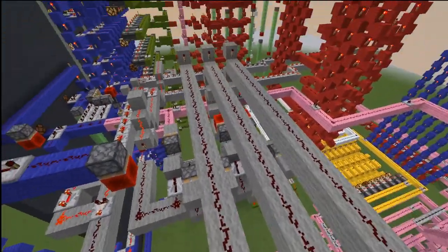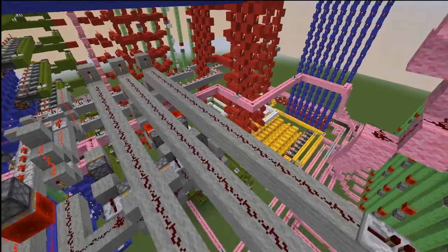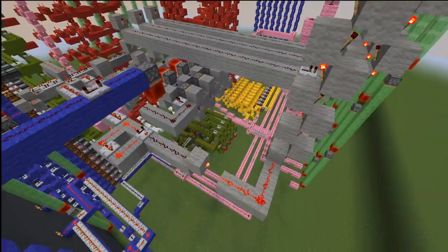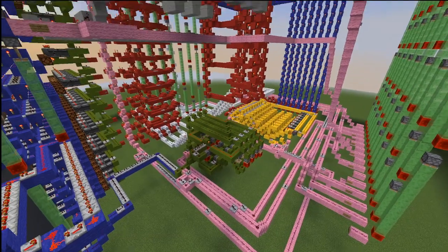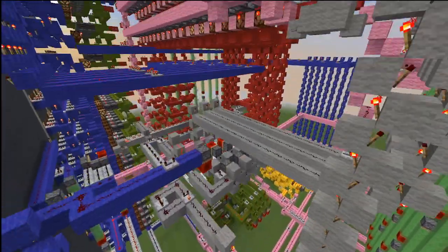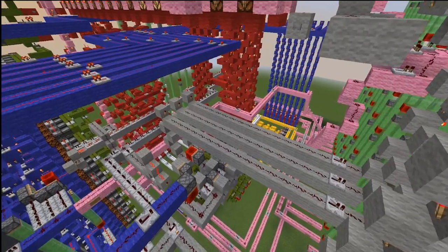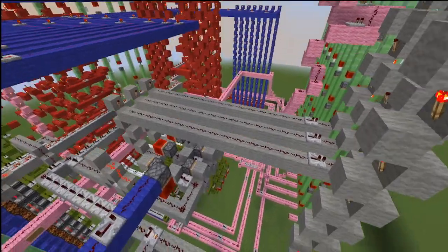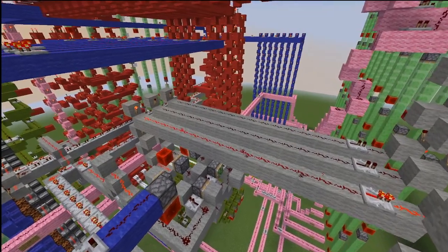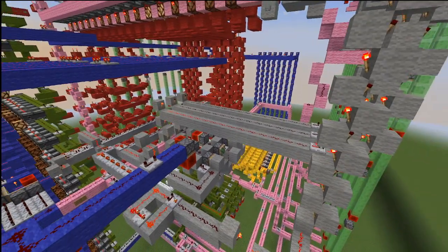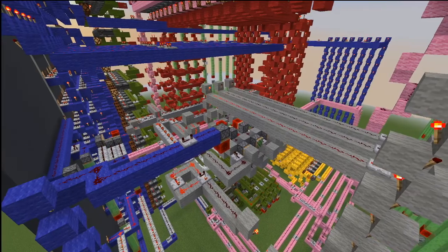Once it hits 1, 0, 1, that's when it triggers the command down here to set the program counter to 8. Or it'll just set it to whatever you put in the address line. But for our program, there's an 8 in the address line, so it set the program counter to 8.